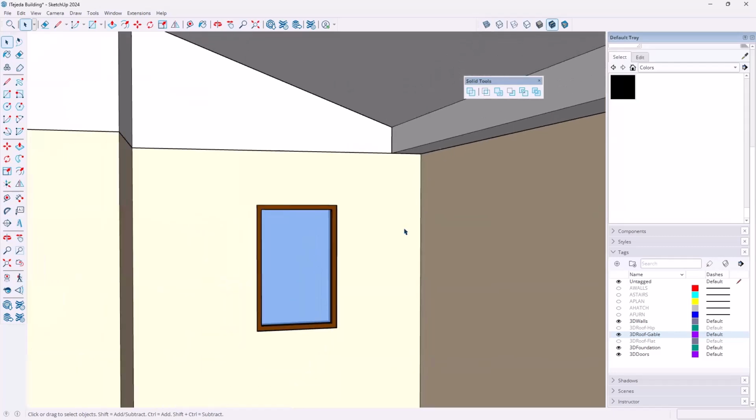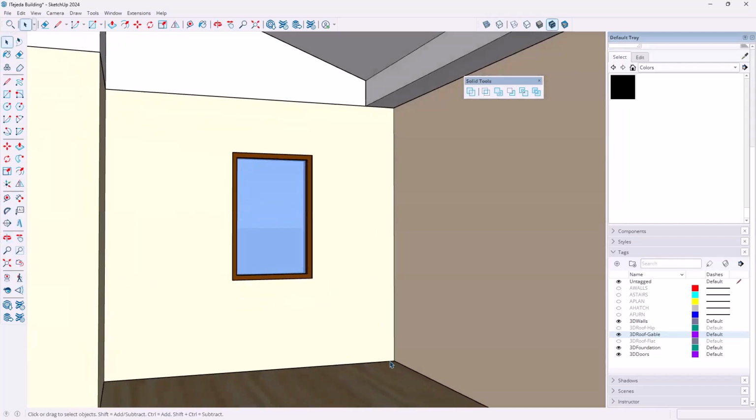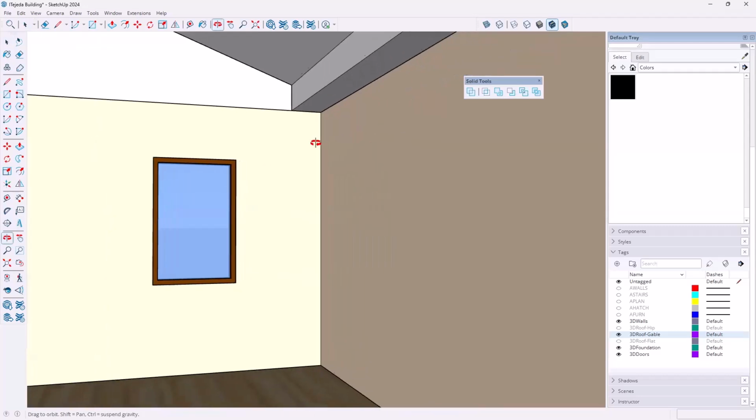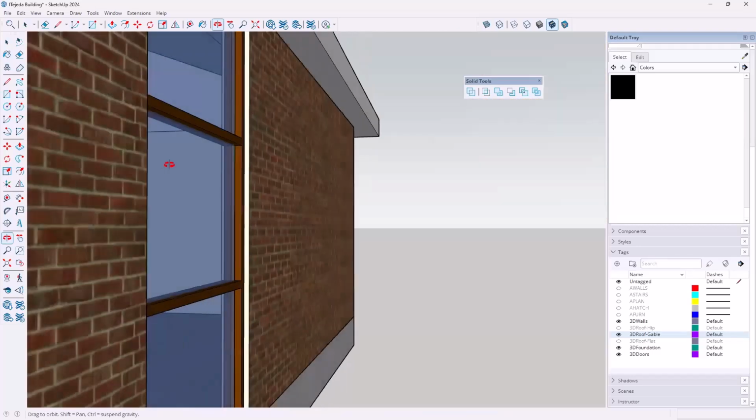And I know that my ceiling height, I want it to be exactly either 8 feet, 9 feet, 10 feet, whatever the case is. But a 1 inch difference is not a big deal because it'll keep you from having to edit the model even more. It's a little shortcut. And nobody's going to notice a 1 inch difference. It'll be fine. So you decide what you'd like to do.